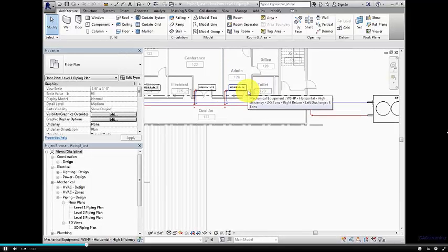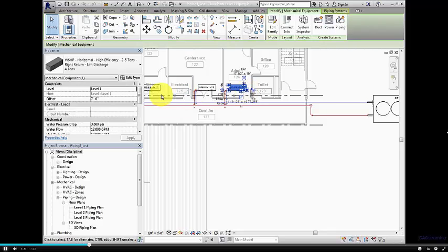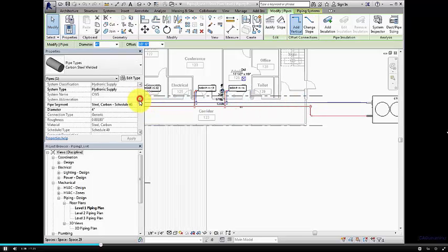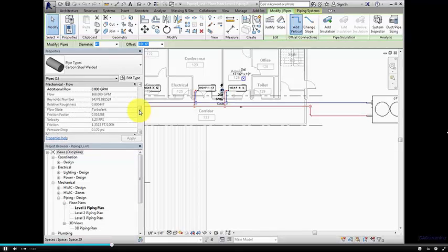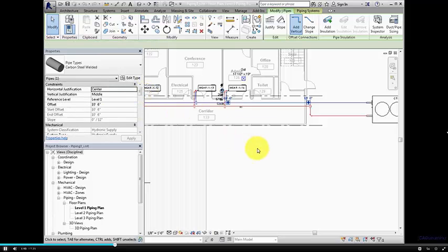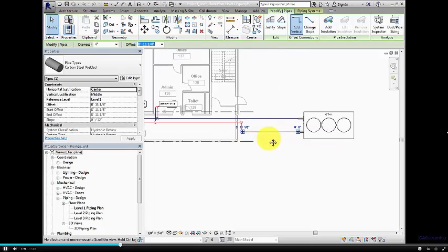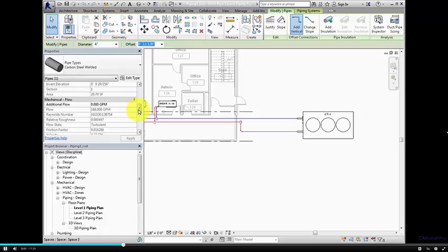For example, when you select Water Source Heat Pump 1-14 in the Properties palette under Mechanical, you can see the water flow. When you select a pipe segment, you can see the flow information in the Properties palette under Mechanical Flow, such as the flow, Reynolds number, flow state, and velocity. Begin by sizing some of the condenser water return segments. Select the horizontal pipe segment connected to the cooling tower. Looking in the Properties palette, you can see that the flow is 168 GPM, or 10.64 liters per second in the metric file.